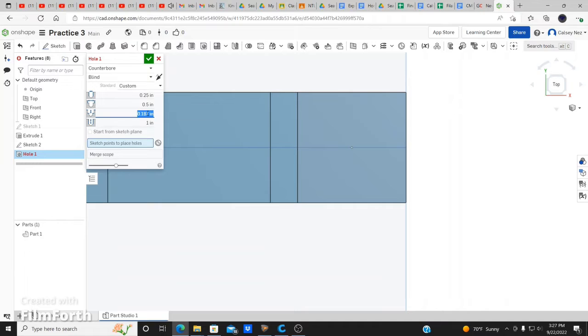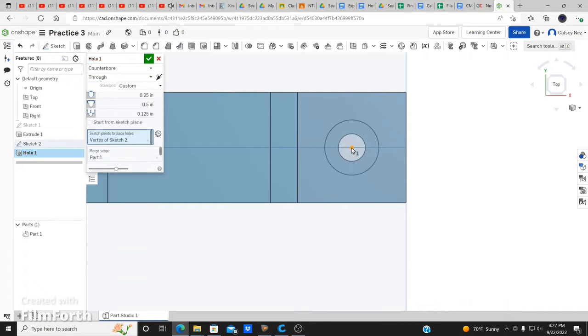This right here, we do have to worry about that. Our depth is gonna be about 0.125. Enter. I'm not gonna do blind, I'm gonna do through. That's the one where I'm gonna activate it, so it'll give me just instructions only. That's it. Once you set in your dimensions in this custom area, I'm gonna go over here, click this one, the center point that we created, and that's it. That's your selection that you want to choose, that point.